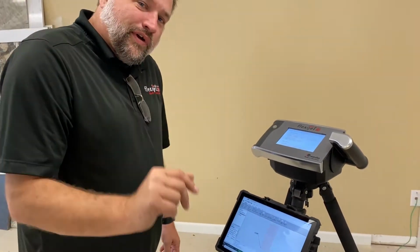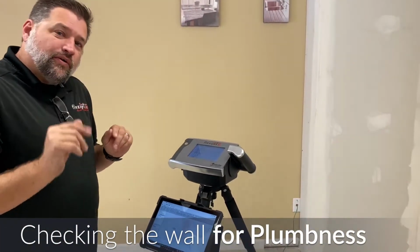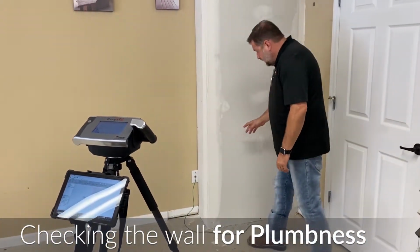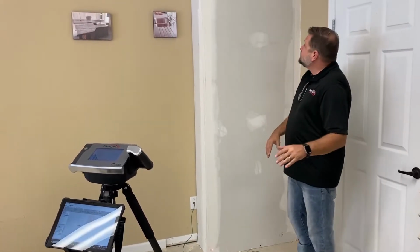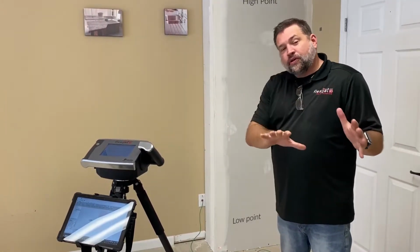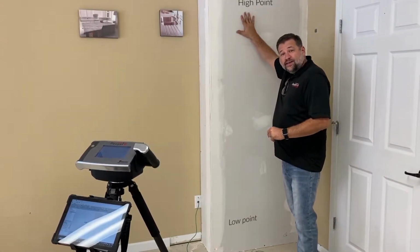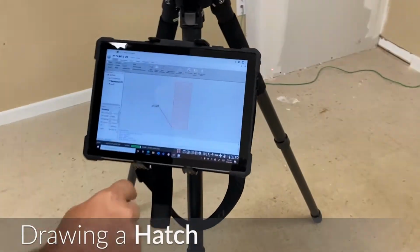Okay guys, what we're going to show you now is how to check where that wall's in and out of plumb. So why this is important, if we establish where a beginning point is, we're going to do a scan grid. And then what's nice about the Flexijet is it'll go back and it'll point us where the low and the high spots are. That's going to save you a lot of time in install, because if you're communicating to your installer, you can go ahead and know where to float the mud out. This also works the same in countertops as far as putting shims down. So let's take a look at what we got here. You take a look in the screen.